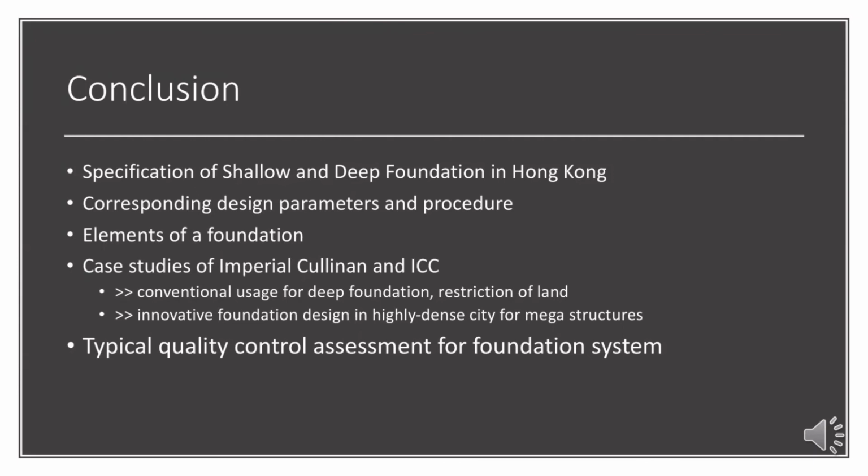The case studies of the Imperial Cullinan and the ICC have shown that deep foundations are commonly used to fulfill the load-bearing needs of high-rise buildings. However, sometimes, due to the land restriction in Hong Kong, innovation in foundation design is required to be capable of constructing load-bearable megastructures in this highly dense city. Last but not least, we introduced the PIT and the CSL, two typical assessments of quality control for foundation systems.